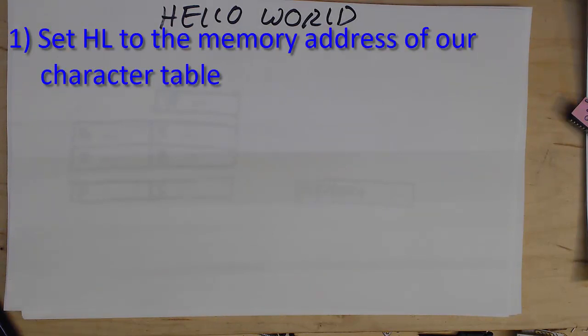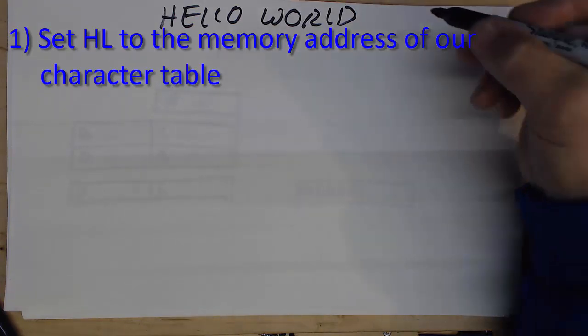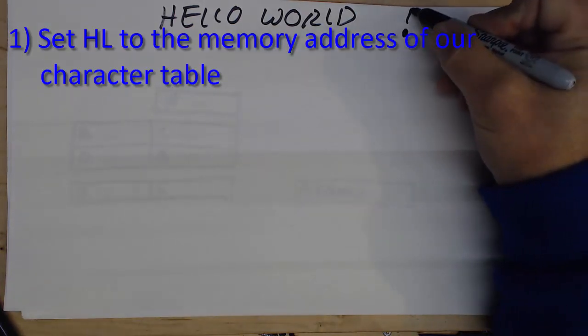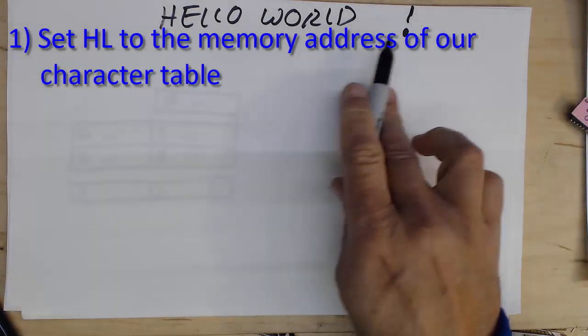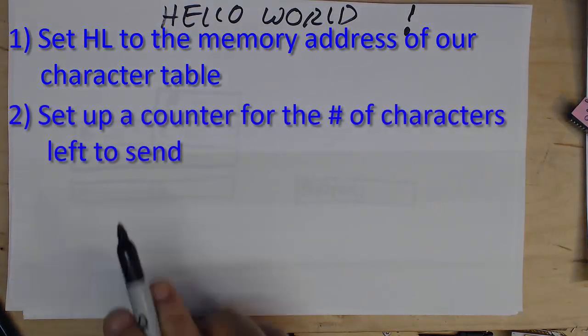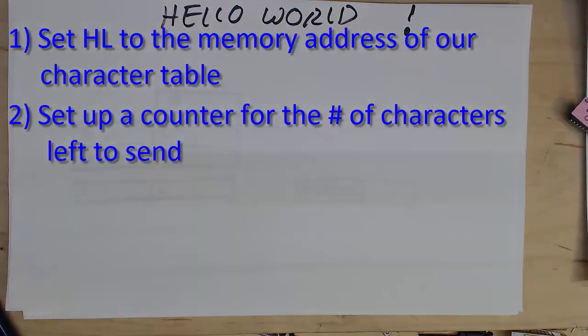We're then going to set up a counter. We could use a delimiter, like maybe an exclamation point, and when we got to the exclamation point, we'd know that we were done outputting this character string. But instead, we're just going to use a counter. We're going to output the 15 characters, so we'll set up a counter and count it down with each character. Now we're going to have our loop.